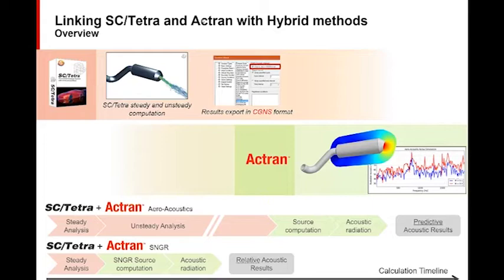So the aeroacoustic sources are computed using what we call an aeroacoustic analogy. These analogies are based on one main assumption, which is that turbulent flows create an acoustic field, but the created acoustic field does not have any effect on the flow. As you remember from the introduction that Sunil gave, the pressure fluctuation of the acoustic fields are extremely small compared to the fluctuation created by the flow. So in most cases, this assumption is valid. There are only very few specific cases that do not satisfy this hypothesis.